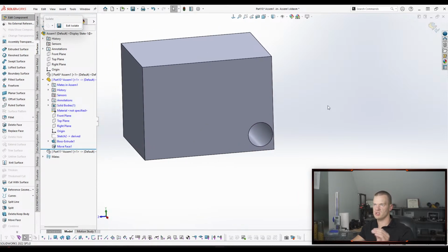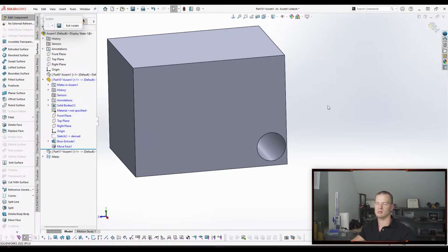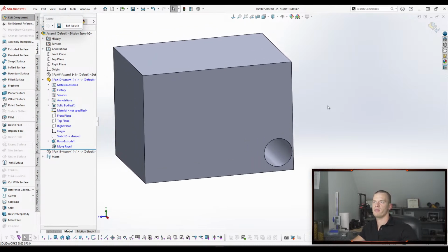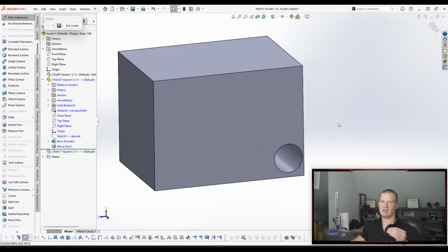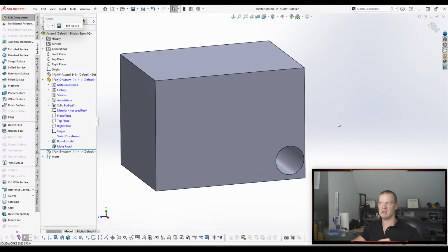And the original sketch is much cleaner. And so that is one thing that I like about doing the gaps. I can prescribe them where I need. I can use interference detection to find them. It keeps my nominal geometry the same across parts, and then I can tolerance up or down depending on what the situation is.